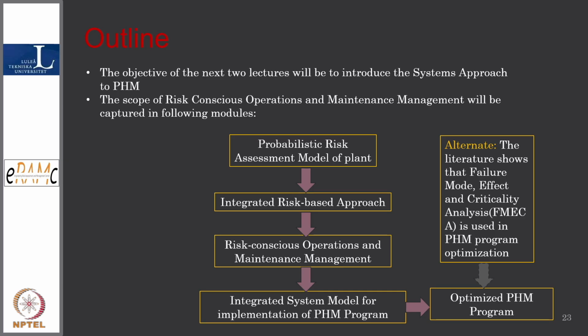What this model says is that it integrates all the components and their performance. The component could be a safety system or a process system. Process systems appear in the inventory, and safety systems also form a header of the inventory. We will see what the inventory and the fault tree are. Safety systems are analyzed essentially using the fault tree approach. And fault tree and inventory together, in a broader way, create the probabilistic risk assessment model of the plant. So, this is one level.